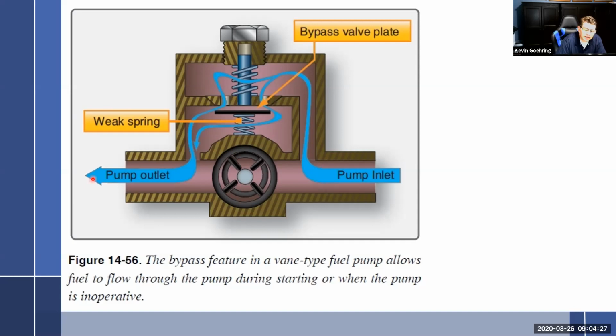In the carburetors that we talked about, I told you how the carburetors don't have enough airflow on the starter to start them. So you had to have a primer. Once we get into aircraft that are fuel injected, and even a lot of aircraft that are pressure carburetor, they don't have any sort of primer system. Engines with fuel injection rarely have a primer system.